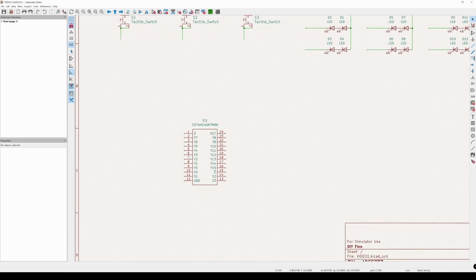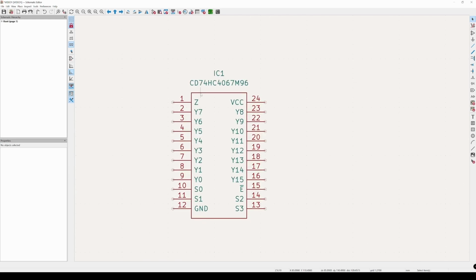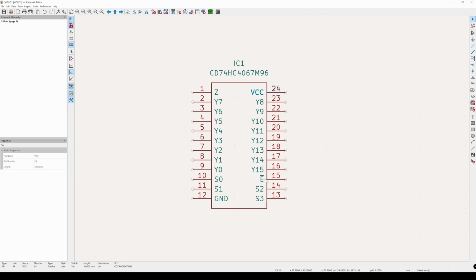We need to wire all of these pins in. Now this is where your schematics or that data sheet will come in handy, or knowledge of the components. You need to know how this needs to be wired. But also the schematics usually do say, or if you create it yourself, you need to name the pins correctly, so it makes things a lot easier. You can see at least we have the ground, enable, and VCC pins here, and those are going to be the simplest connections that we have. Ground enable is going to be ground, and VCC is going to be 5 volts in, or you can name it just VCC.